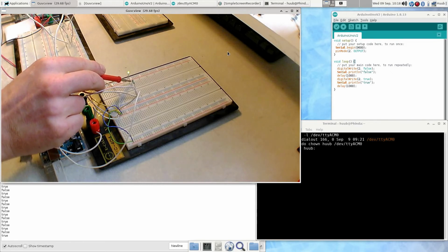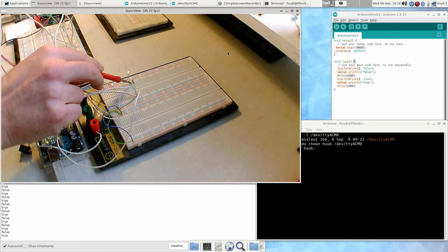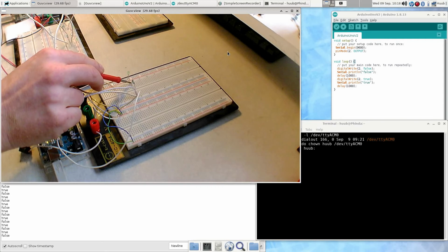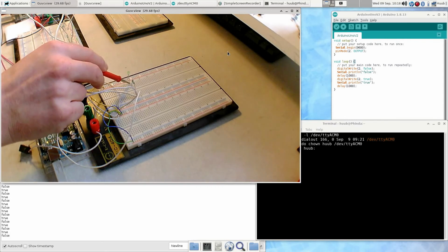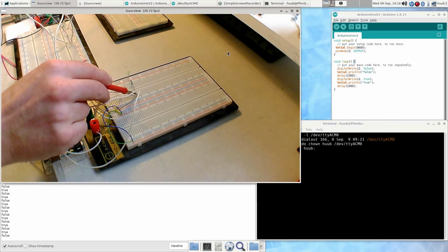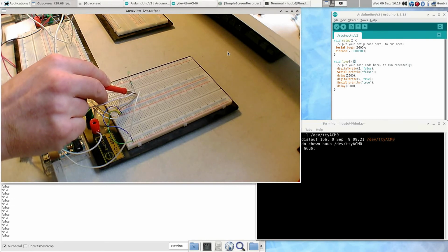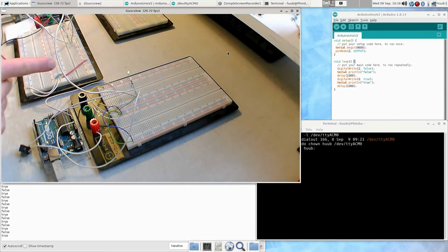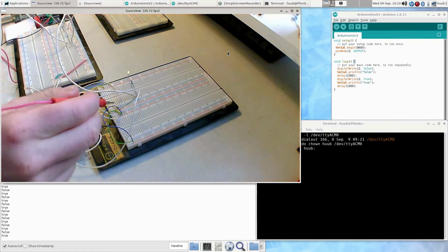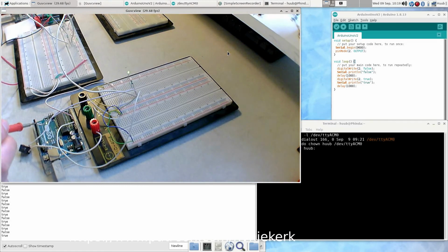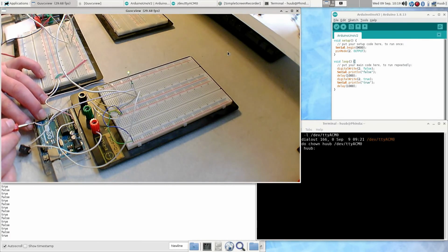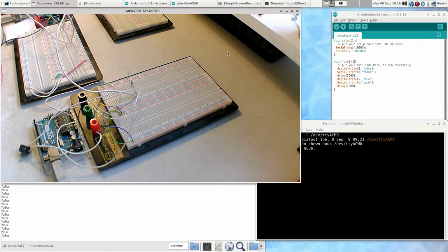nothing, or very low voltage anyway. What do I measure here? Very low voltage. So it's not the wire. It is not this wire. So what should I do? Measuring right here. A very low voltage. So the very low voltage is not by wiring, it's coming from the system.